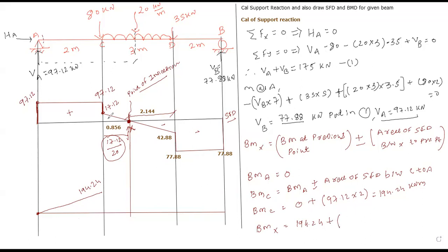Now, what is the area of the shear force diagram? What shape is it? Type the name of the shape in the chat box. What shape do you see from c to x? I am shading the shape I am talking about. Okay, triangle. Good. What is the area of a triangle? 1/2 base into height. Yes or no? In the calculator 1/2 cannot be written, but you can write 1/2 as 0.5. I am writing 0.5 here. Write 0.5 multiply by what is your height?